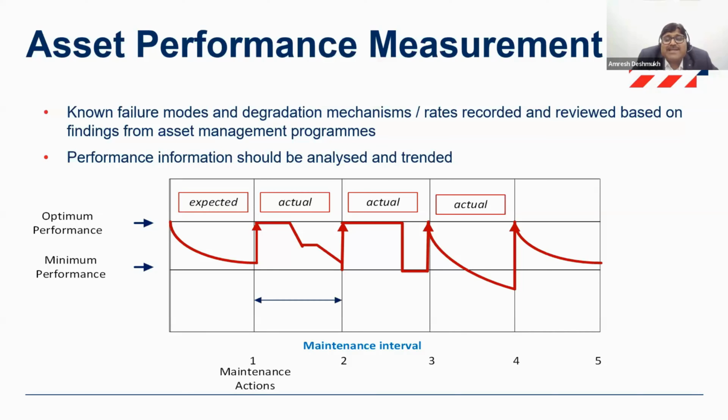So if you look at cycle number 2 or cycle number 3, there is some scope for you to modify your maintenance program for this type of equipments. You can relook at the frequency at which you are doing preventive maintenance. Now, this is in reference to the critical assets. I'm not referring to this particular graph with respect to the other assets, which are not a part of your critical equipment list.